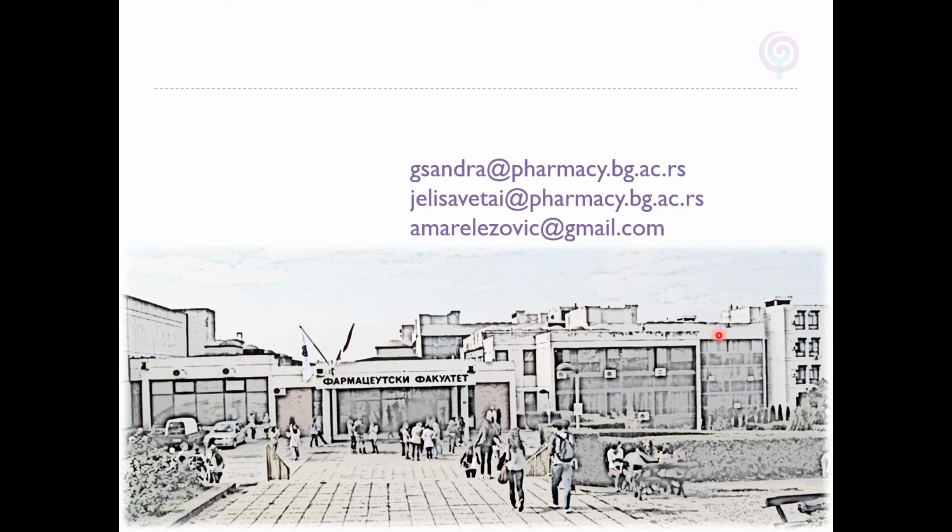But later on, when the new version of GastroPlus arrived with the option to include lysosomal trapping, I tested the software's integrated option to take this phenomenon into account, and the results were quite similar, although the decrease in Cmax and the prolongation in Tmax when I included the automatic function of lysosomal trapping was somewhat lower than the one we obtained with a 50% reduction in KP value. So it would correspond to about, I think, a 30 to 40% reduction in KP value. And now it is much easier to simulate such phenomena, but at that moment we had to trick the software.